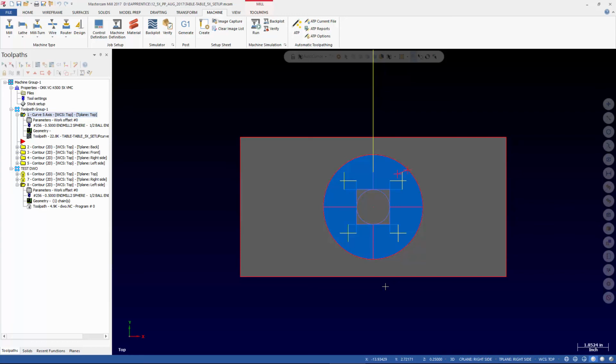So we just took the generic Fanuc 5x mil post, and in about an hour, we went through and showed not just setting the values. I can do that in 5 minutes, but really hopefully helped explain what each one of these positions does and how you can tell if you're set 90 degrees off or 180 degrees off.